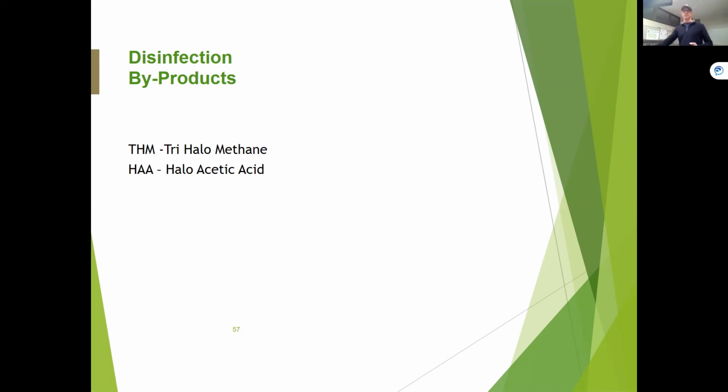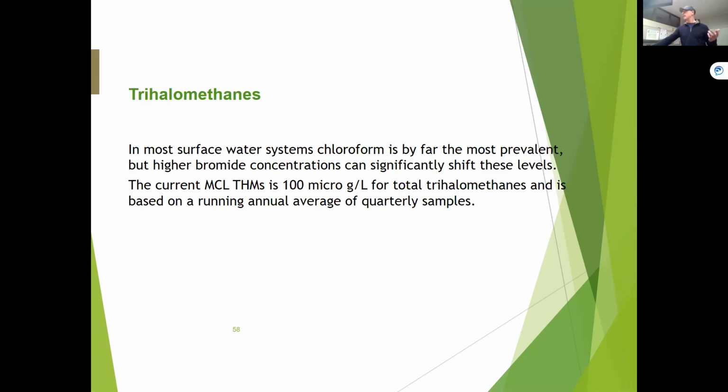The one big thing about trihalomethanes is that, again, we know that chlorine is used, and it has to be used because most of our regulations need residual protection. And chlorine's the only thing that's going to give you a residual protection that we measure. Again, chloroform is one of the trihalomethanes. And when I look at my water quality tests, when it comes back, chloroform is usually always the highest. That's usually the biggest one that's formed, or the one that forms the easiest. Also, we see some bromo or bromide type concentrations. I see a lot of those.